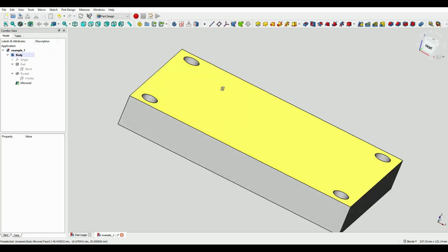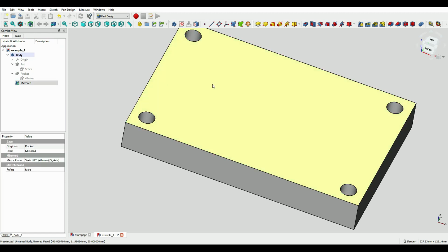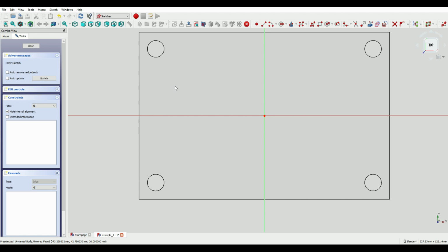As you can check bottom up, everything is okay. So what we're going to do is click on this face again, click on the sketch. This time we're going to create a polar array of 6 holes surrounding a center location. So this is what we're going to do.